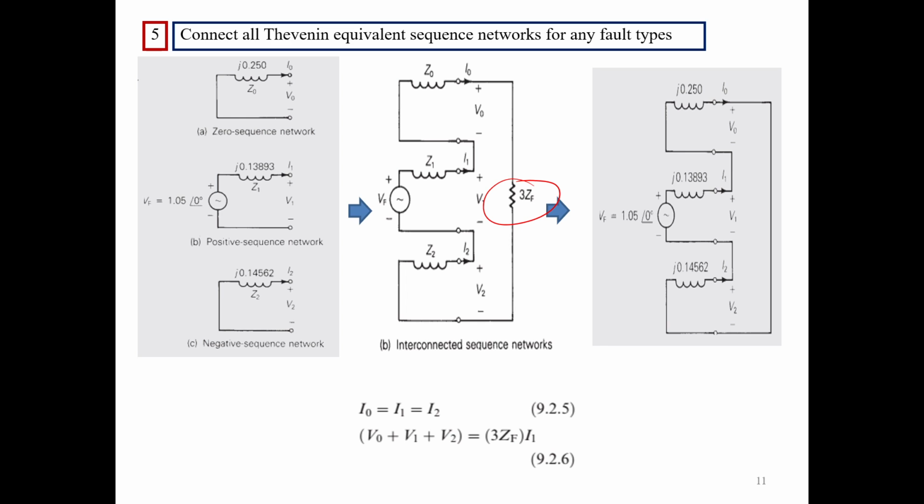The problem specified that it is a bolted fault, so ZF is zero. Zero impedance means a bare wire. So this is the interconnected system.